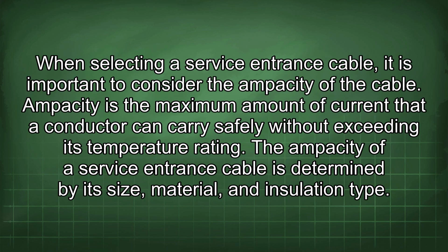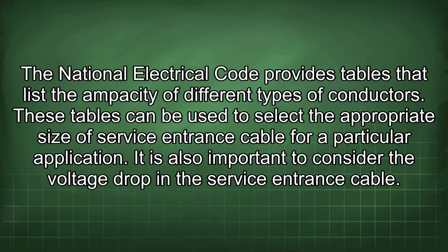When selecting a service entrance cable, it is important to consider the ampacity of the cable. Ampacity is the maximum amount of current that a conductor can carry safely without exceeding its temperature rating. The ampacity of a service entrance cable is determined by its size, material, and insulation type. The National Electrical Code provides tables that list the ampacity of different types of conductors. These tables can be used to select the appropriate size of service entrance cable for a particular application.